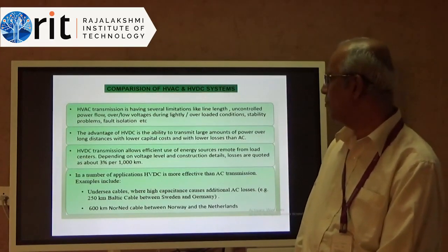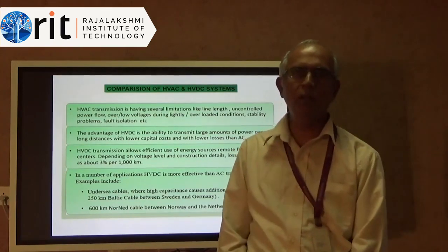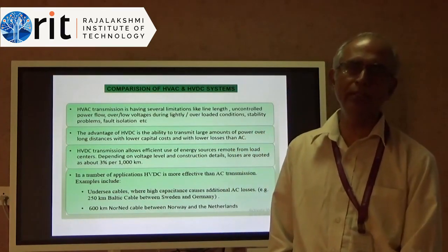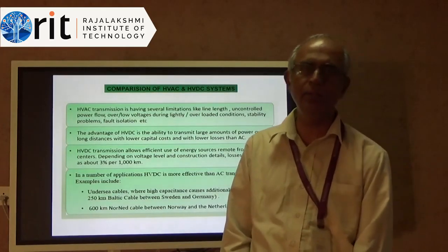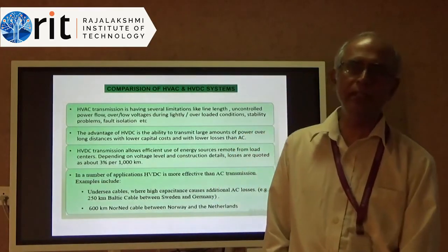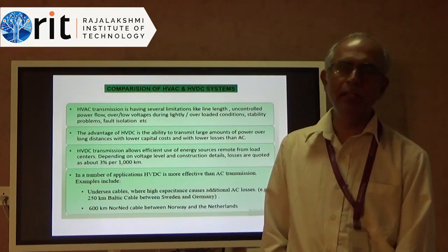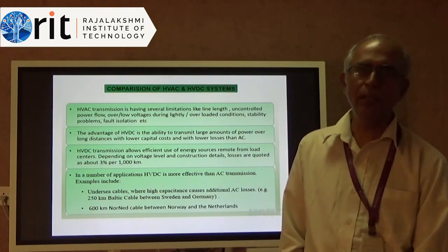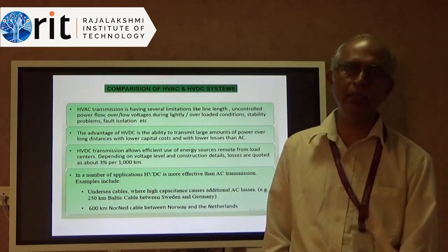So the advantage of HVDC is the ability to transmit a large amount of power over a long distance. As we said, for DC there is no difficulty about reactance, resistance is the only parameter which influences a DC transmission. So you have no limitation on the length of the line. A 1000 kilometer line is also feasible. In fact, there are lines existing in Europe which connect one country to another country.